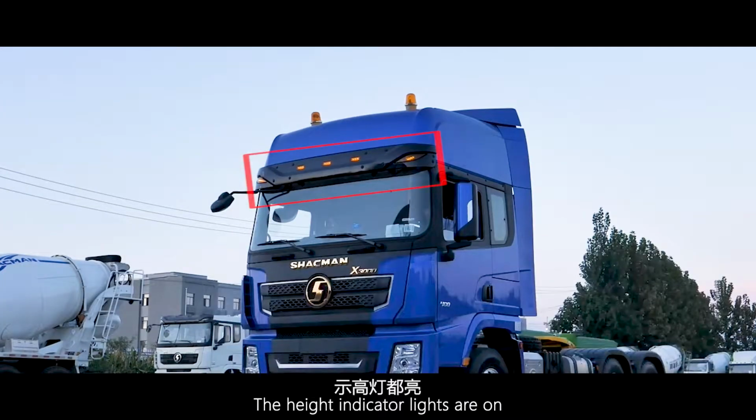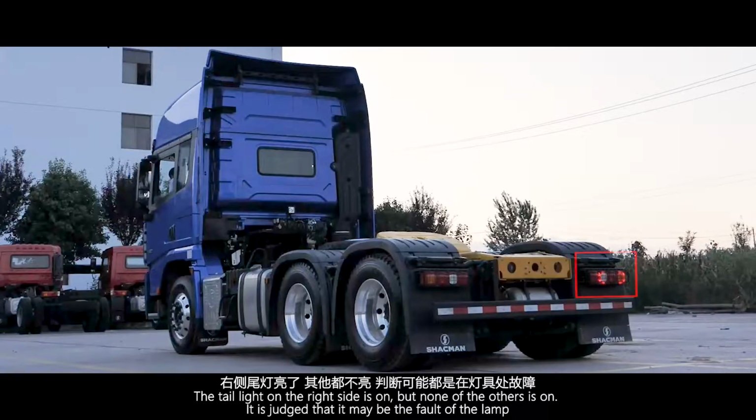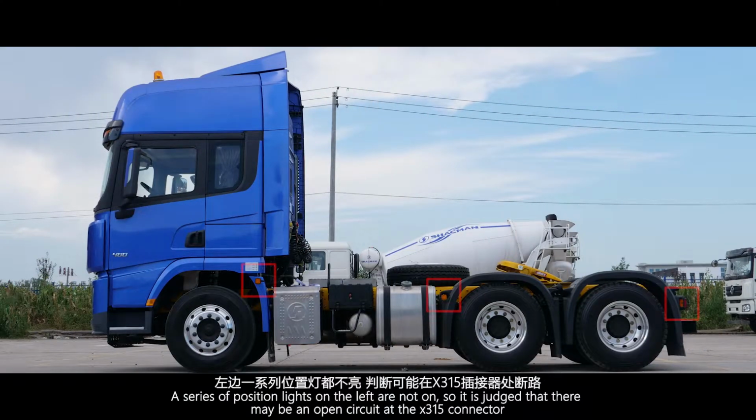The height indicator lights are on. The tail light on the right side is on, but none of the others is on. It is judged that it may be the fault of the lamp. A series of position lights on the left are not on, so it is judged that there may be an open circuit at the X315 connector.